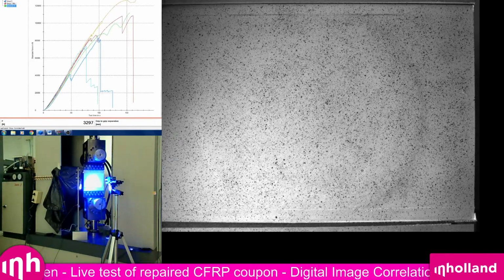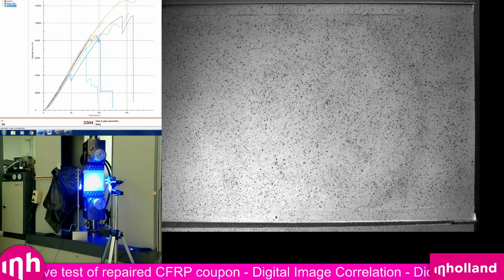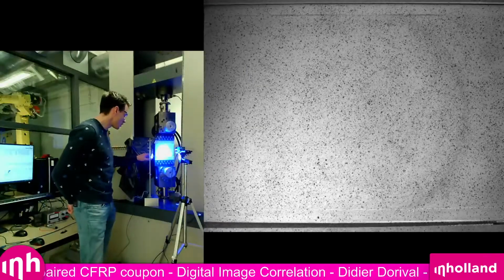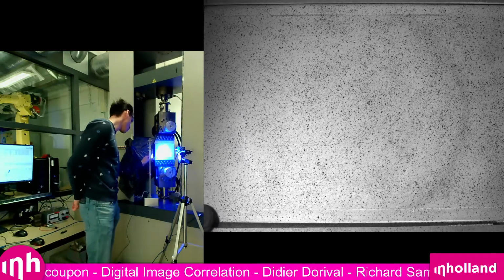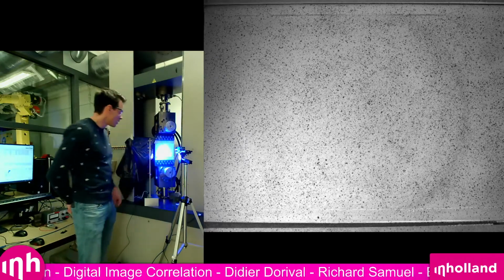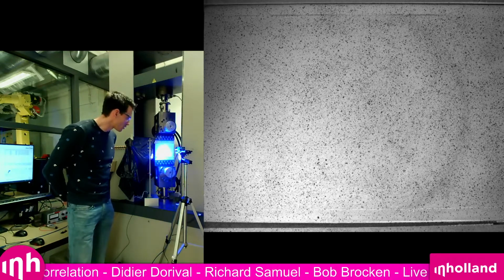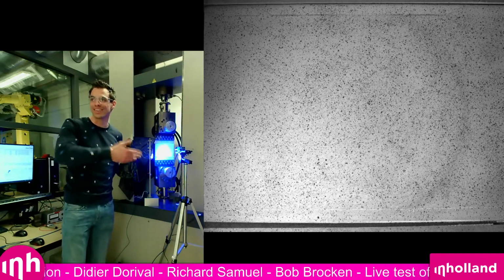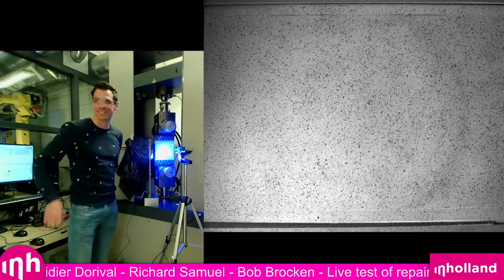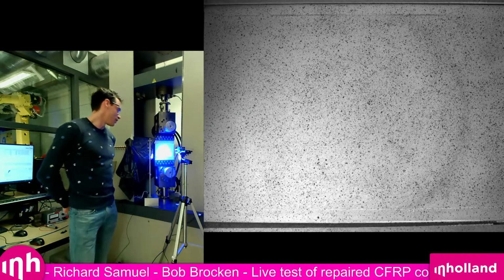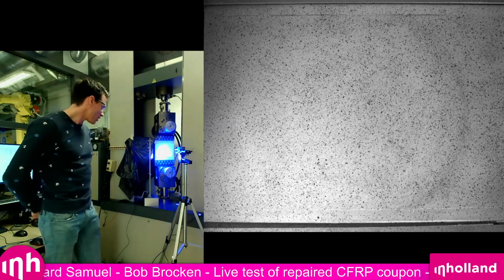So, field test. Maybe you can explain. As you can probably see as well, at the bottom edge of the sample you actually pulled the sample out of the alu plate, which indicates that the sample failed somewhere within the clamping, which of course it shouldn't. This is test number 7; the previous 6 tests actually broke neatly in the middle.